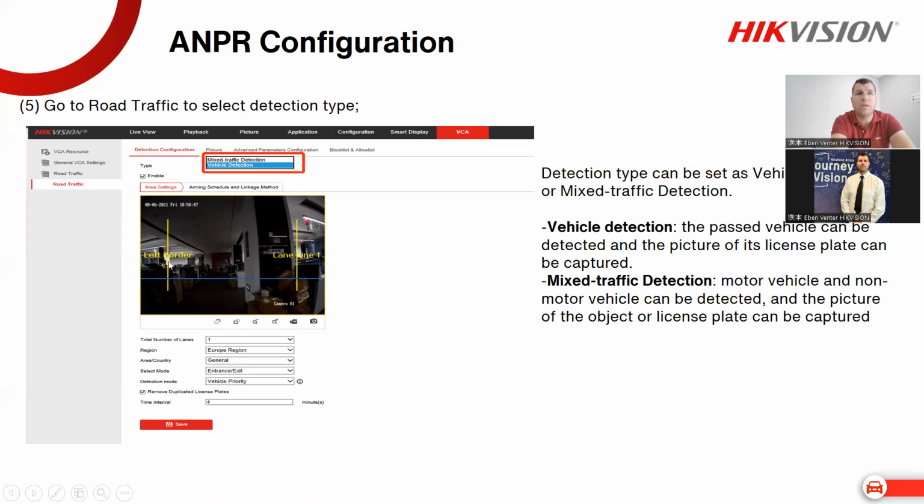So as you guys can see, you have the normal way of doing things. You have this border line. Once you have that borderline, that's you telling the camera that it needs to focus for the number plate in this specific area. Then we have our blue line. That's when the vehicle crosses the blue line and it will take those little snapshots and put them together and give you the different output of that number plate.